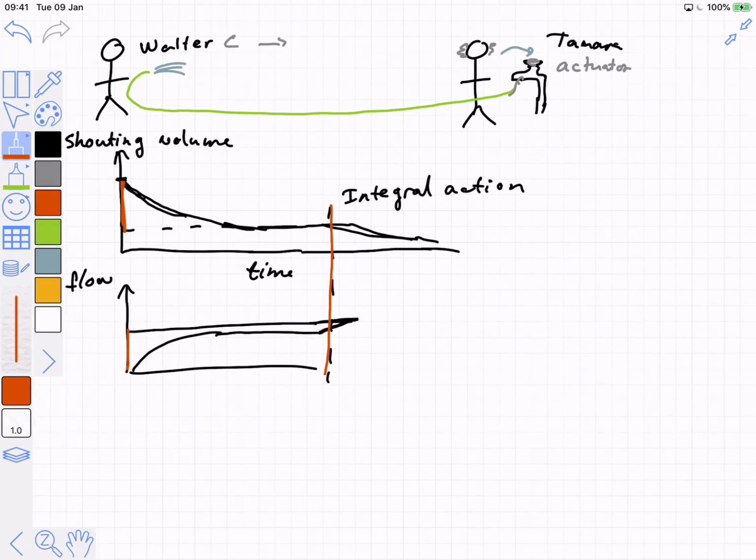In most cases, the math that maps to this is that the action is going to be whatever the basic action is, whatever the normal output is, plus some factor times the error. Well, let's just say, I'm going to write this out separately. Some factor times the error plus another factor, which usually we write like this, times the integral of the error.